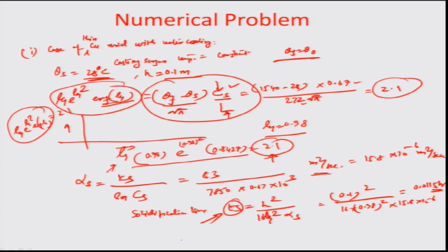As regards the estimation of the time of solidification for the second case, we will see that there is slight variation in the time of solidification. In fact, it is going to be a little more than this case, because obviously we are adding more resistance to the heat flow path by taking also the mold as a sink in the thick copper mold case. So, let us do that problem now. So, for the thick copper mold without water cooling,